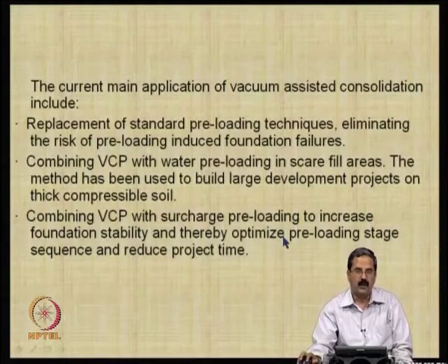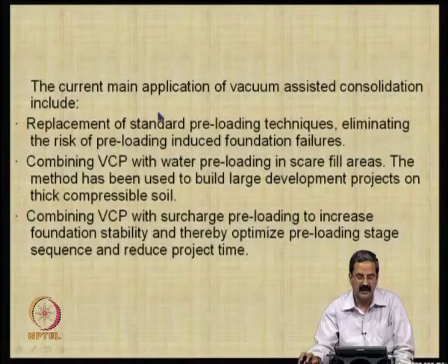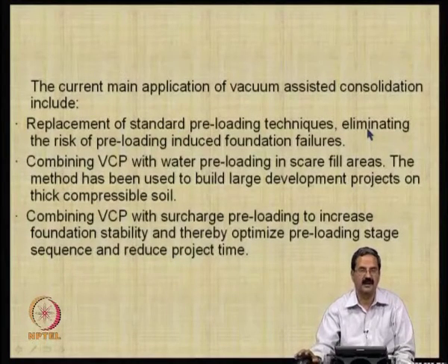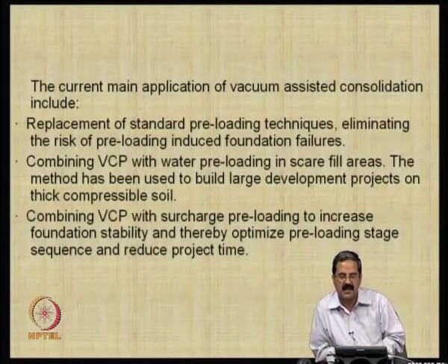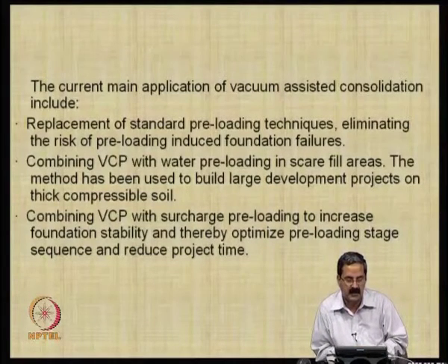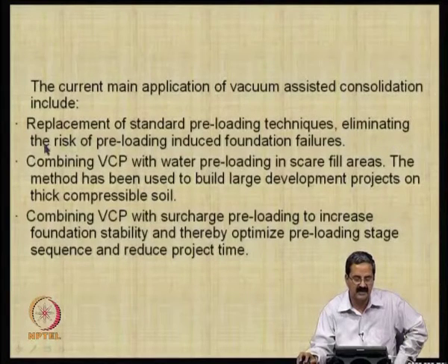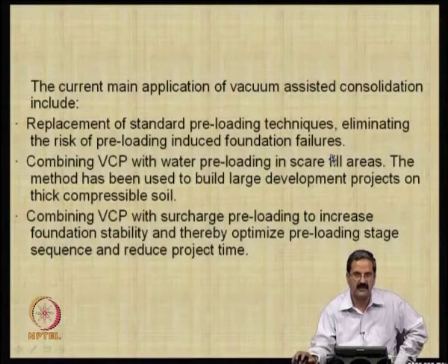What we are trying to see here is that the current main applications of vacuum assisted consolidation include replacement of standard preloading techniques. Standard preloading means adding a lot of sandbags and other material, and the problem is that it carries the risk of preloading induced foundation failures.